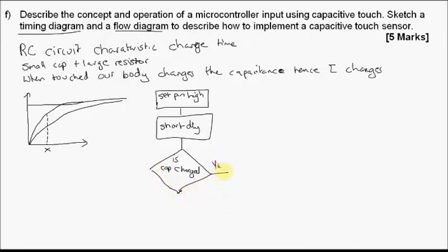If yes, then we're not pressed, because we've followed this route and the capacitor's charged up enough. If no, we're pressed, because it's taking us longer to charge up because our time constant's long.